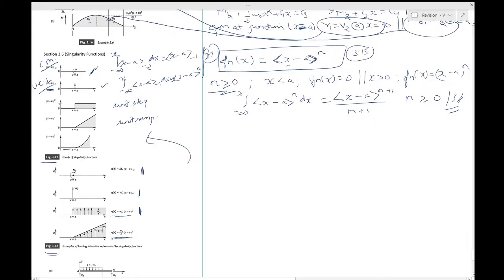It's not that there are only these 5 functions, there are a lot, but for our problem these 5 singularity functions are enough. Most practical cases of beam bending can be built by superposition of these cases. This last one will seldom be used.